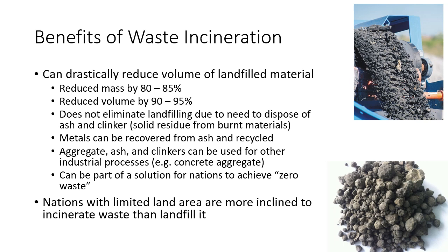So there are some benefits of incinerating waste as opposed to just sending all of it to the landfill. And I'm not going to go into the materials that should be reused and recycled, which we'll talk about on another day. Let's just say that the options right now are landfill or incineration, and not think about recycling for a second. It can reduce landfill mass by 80 to 85% and the volume by 90 to 95%.